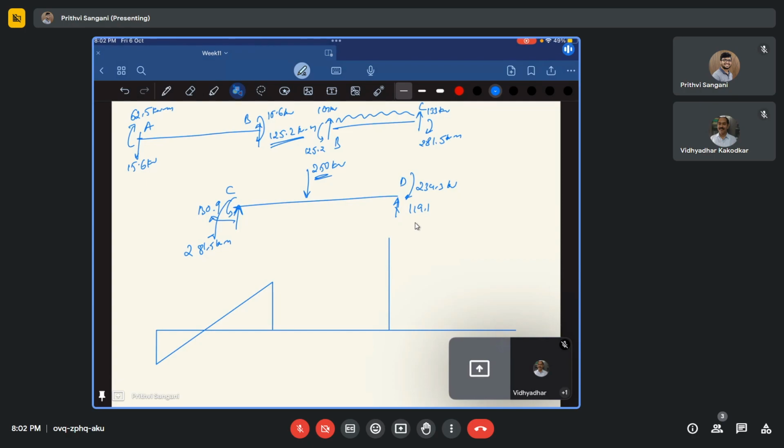So you can actually see at the mid span that this is going to be positive. Okay, at the mid span, the bending moment is going to be positive. That means it is actually going into a double curvature. So what I'll do is I'll just try to draw, assume this as parabolic. Okay, so this is how it is, and after that